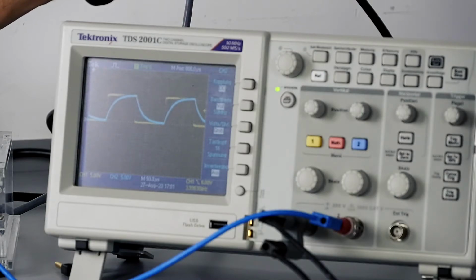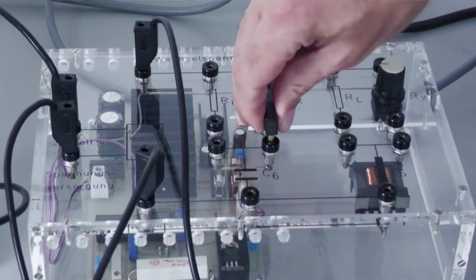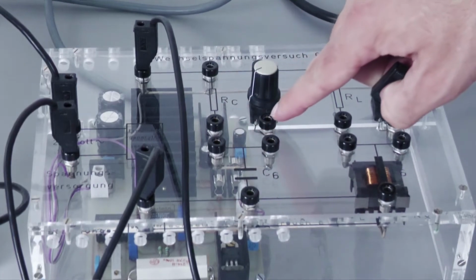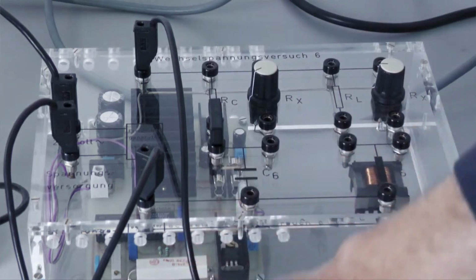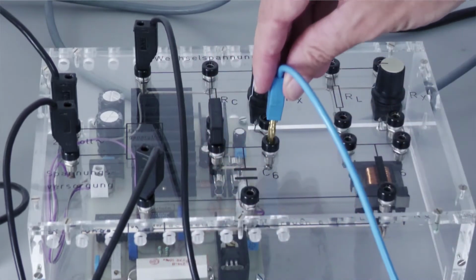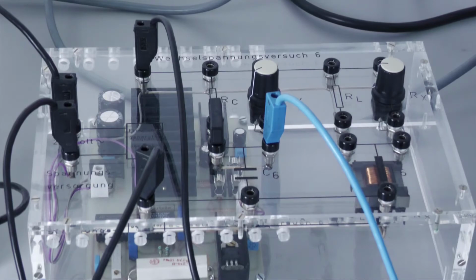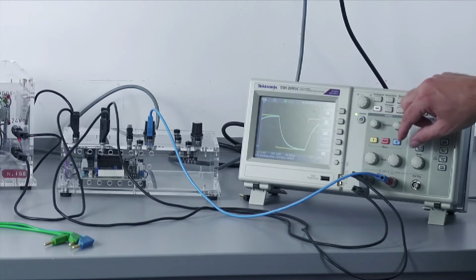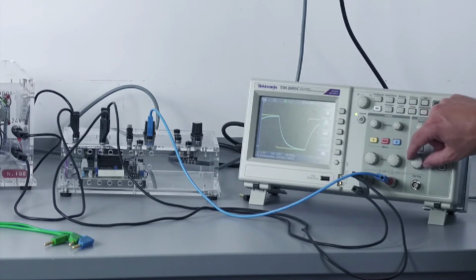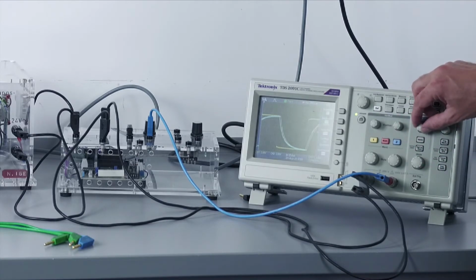Now we measure the capacitance of a capacitor with the oscilloscope. Connect the fixed resistor to the capacitor. Show the charging curve of the capacitor with best possible time resolution on the screen and measure the voltage at the capacitor as a function of time. Save again a corresponding picture for evaluation at home.